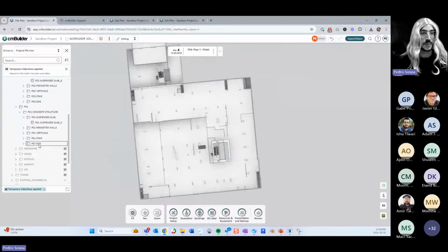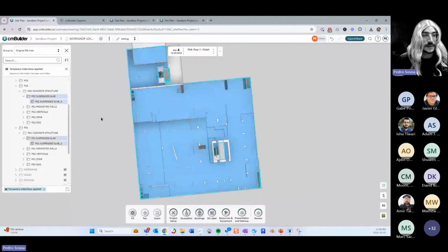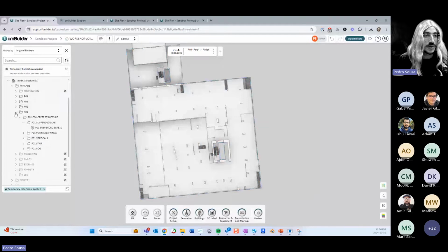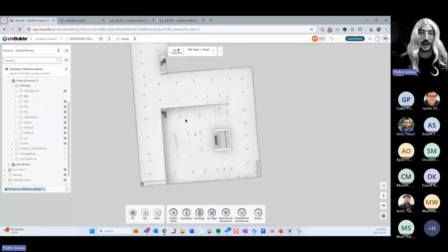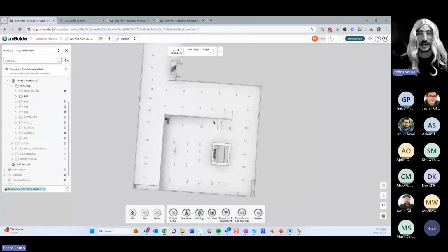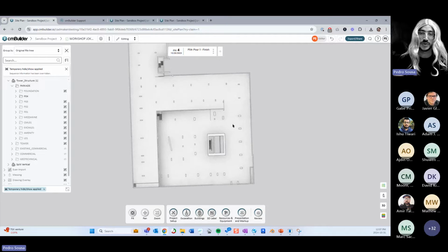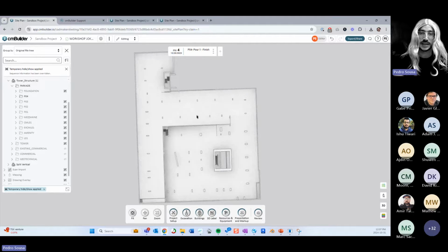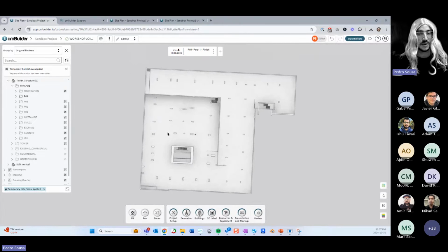Okay, so let's check, starting with our P4. I want to create pour breaks where I slice this model here, and then have two slabs, isolating this area and this area. So I'm going to do one pour break first so you can see how it works.